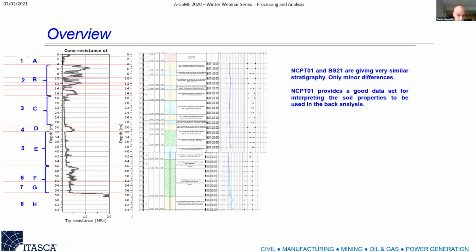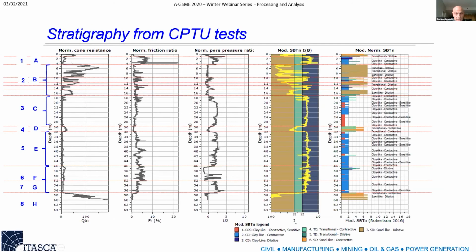And then we started asking for CPT. You see the soil layering and the evaluation all the way down to essentially 60 meters until we have a competent dense sand. All this material is very compressible. And here at the top, we have a sandy, silty material. All the profiling that you can get from the CPT, you get a lot of information.